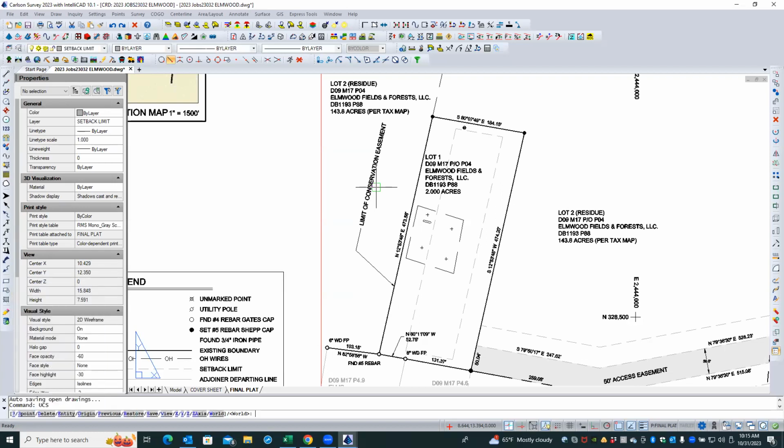Okay. Now I'm not sure. I'm checking if we can do it through picking into this model space or not. We'll see. I think we can, because we're not rotated relative to it. So I think we're all right. But now I said UCS, and I've got all these different options, one of which is, you see that letter E for entity right here? That means match an entity's rotation. So if I choose that entity, and if I choose this guy right here, blink, it says unable to use that selection, please try again. Okay, so it's not going to let me.